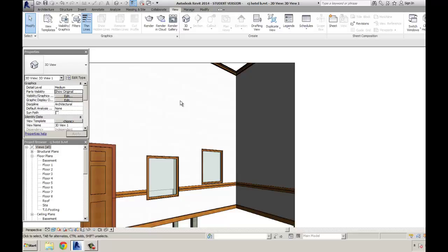So what I'd like you to do, to be ready for our lab this week, is make sure that you create this custom wall type with our trim values in there. And it's just a matter of adding the base, adding the crown molding, creating a chair rail profile, and placing it on the outside of the wall. So practice with that. Really not a lot about this in the book. It's a customizing thing, but I wanted to make sure that you're able to create custom materials and custom profiles and basically optimize the use of this. If somebody asks you to customize these things, it's helpful.